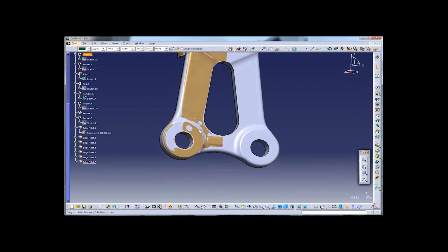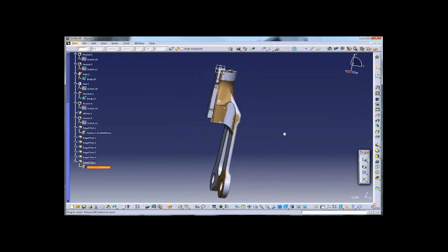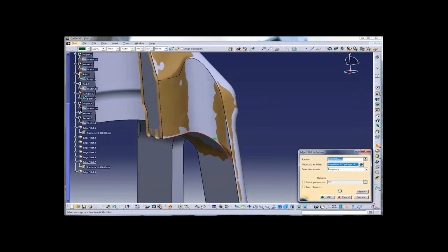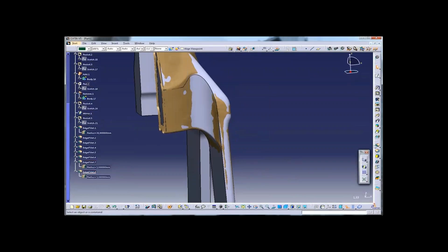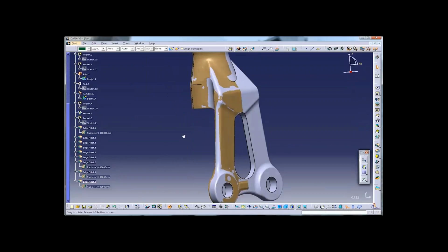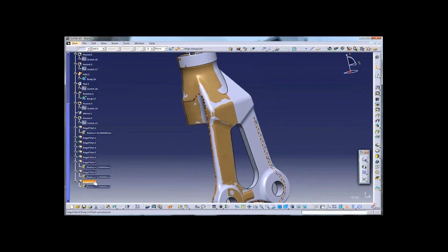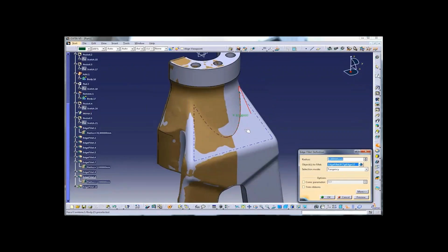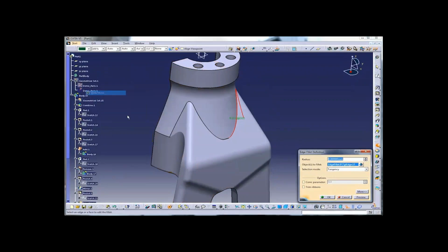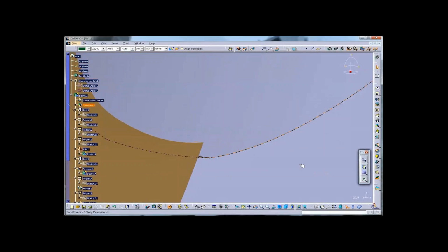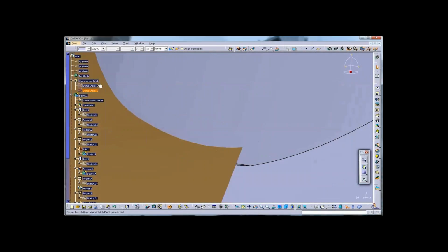So we can inspect our design visually, like you can see right now on this video, or you can also use a tool called Deviation Analyzer, which can find defects in the design, and of course you can go back and change these features as I previously said. So you see here there's a small defect there that I need to modify with some fillets.